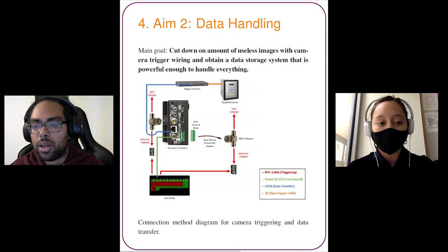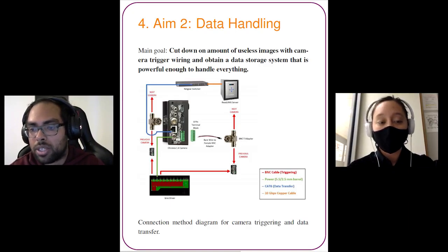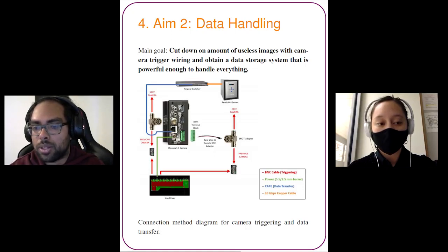Trigger I/O port 2 is an 8-pin terminal block connector. Only 2 pins are needed to initiate recording, a COM pin and a TRG2 port. In the figure, a terminal block has a bare wire to female BNC connector attached to it. This basically converts I/O2 into another BNC connector to simplify connections. Using BNC-Ts and cables, a single ring of cameras can be connected together. The trigger I/O1s for a single ring of cameras can run off a single port on the line driver. The same would apply to trigger I/O2 ports.